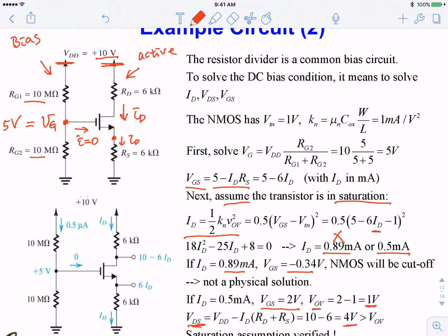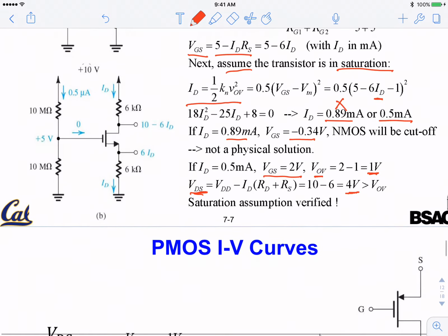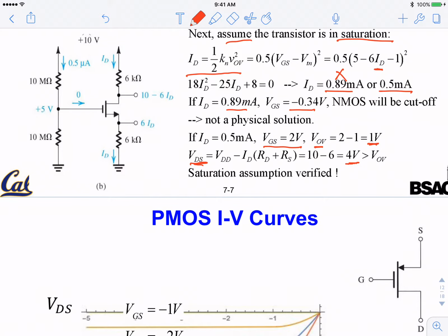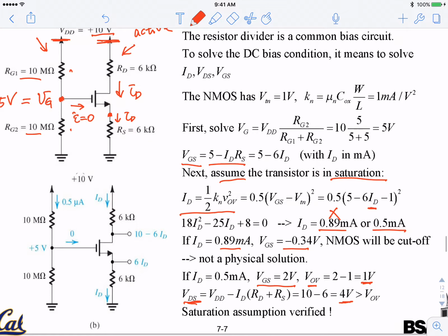This kind of bias that you see for the transistor, this is the four-resistor biasing circuit, is very common for discrete circuits, like the one you're doing in lab 4. It's much less common in integrated circuits. So as we move on, you will see the entire amplifier. You don't see any resistor at all. That will be more commonly used for integrated circuits. Questions here?